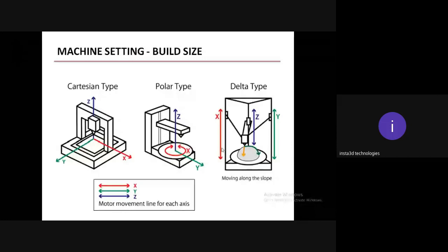If we consider slicing software, after the initial installation of the software or firmware, it will request the print settings, the machine settings. Machine settings means, what is the build area? What build volume can it print? What machine are we using and going to interface with the software?